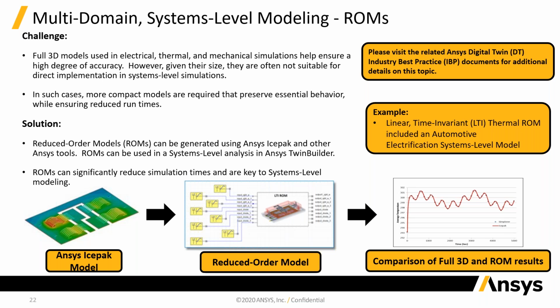What these do is, we can take this as an example where we have a PCB on the bottom left here, and they ran several IcePak simulations on it by inputting a power generation for the components and looking at the temperature as a result of that. They iterated on the amount of power generation in the PCB many times and ran the simulation several times, getting different temperature profiles each time, of course. They then took that compilation of results, input them into the ROM builder, and that spit out the reduced order model.